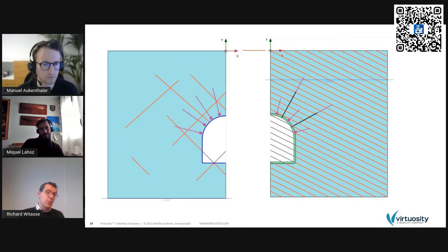With respect to reinforcement, PLAXIS offers a very generic element called the embedded beam, which is perfectly suited for the modeling of rock bolts. The embedded beam is made of a beam, as the terminology says, connected to the surrounding soil by means of non-linear coupling springs with non-linear behavior, meant to reproduce the soil-structure interaction. Those are the elements you could see in purple there. They are well suited for rock bolts and cables as well, to a certain extent, but especially rock bolts.